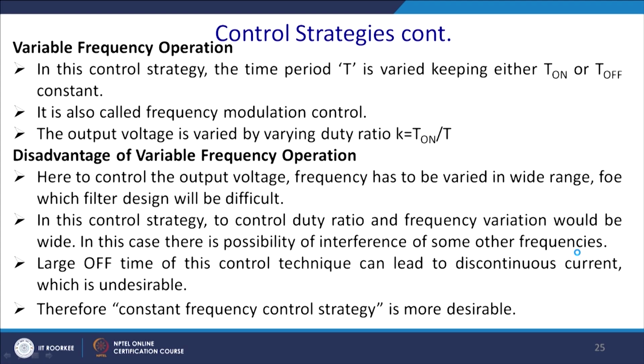Now, let us come to the variable frequency operation. In this control strategy, the time period T is varied, keeping either T on or T off constant, and it is also called frequency modulation control. The output voltage is varied by varying the duty ratio T on by T or T off by T, whichever is constant. So, there are a few disadvantages of